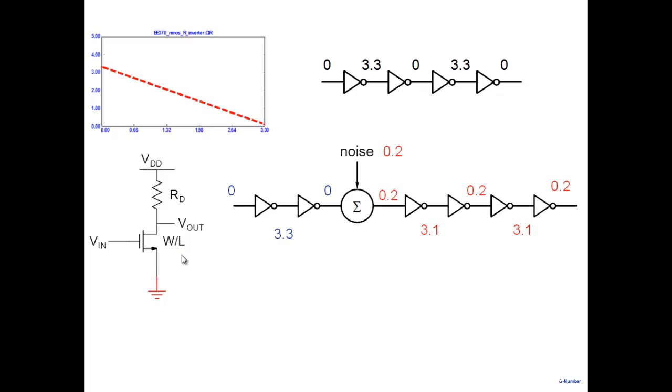And anyway, if you recall, we said that all these transistors are made in the same substrate. All N-type transistors share the same P-type substrate here. So the substrate is common for all of them. And if you have not made proper contacts to the substrate, the voltages from one inverter can get coupled to the other inverter through the substrate. So something which is not intended for an inverter may come through the substrate and start affecting my inverter here. Now, note that if anything gets injected into the substrate, the bias affects the threshold voltage, thereby affecting the currents and things like that.